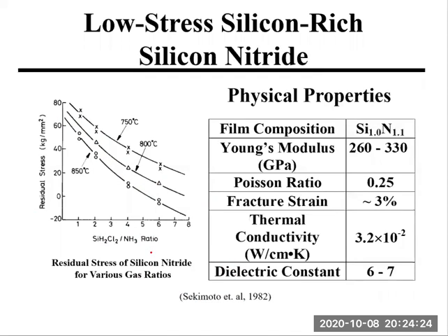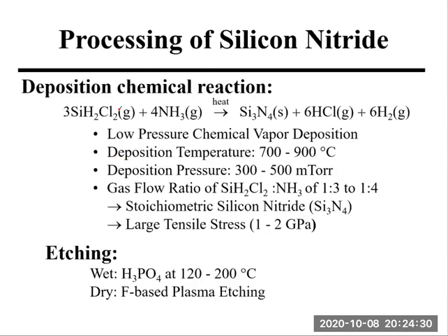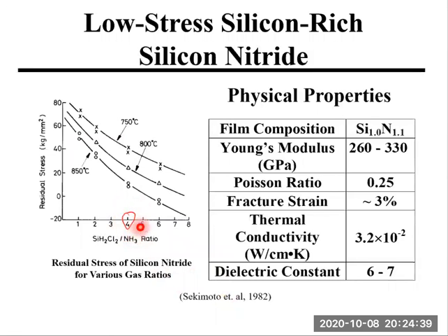So now we have this ratio of 4, compared to the ratio in this chemical reaction. The ratio is 3:4. So with the ratio of 4, there is more silicon required, so we actually kind of overflow dichlorosilane. We provide more silicon than required by the stoichiometric ratio.